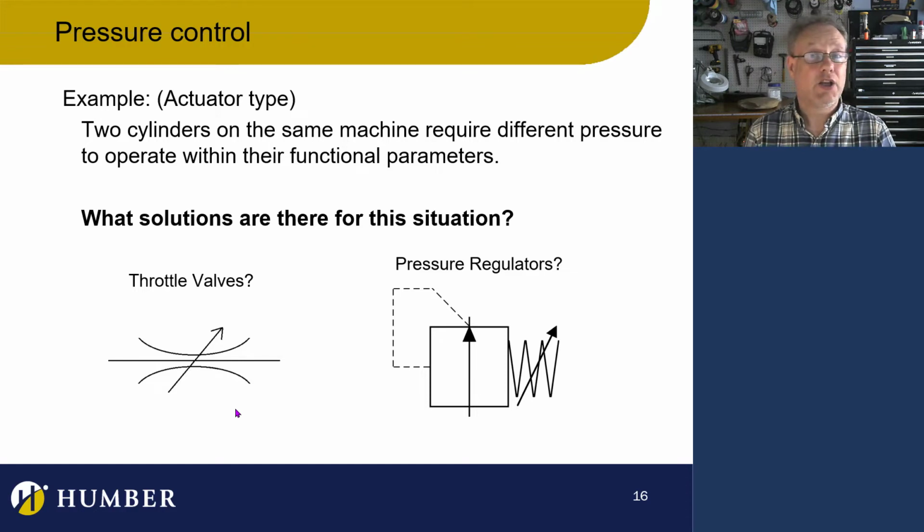So we can say, hey, you know what? If you turn the system pressure on to 80 PSI, and you had a pressure relief valve downstream, say before some actuator, that was set to 75 PSI, it would constantly be venting air. And it would only vent air down to 75 PSI. So any air past that pressure relief valve would actually be at 75 PSI. Now, I just asked you, how do we control pressure? That is a way to control pressure.